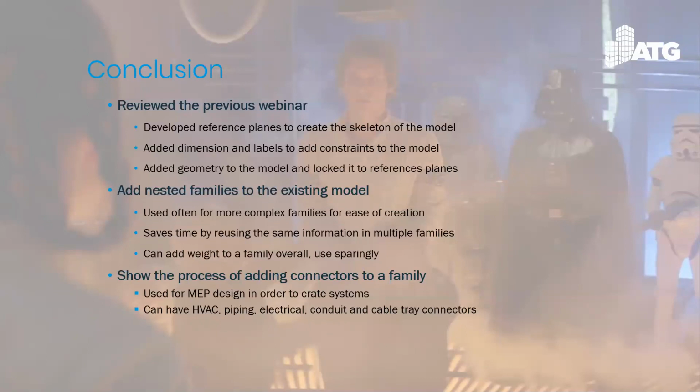Nested families can save you time, but if you use them too much, it can add too much weight to a family. Don't start creating every nut and bolt for an object in a family. That is not a way to utilize nested families.